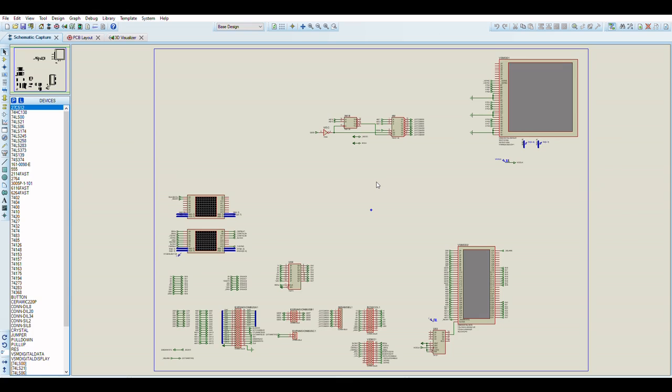So the software I'm going to show you has allowed me to transcribe the original Bomb Jack schematics that I found in a PDF file, and to change the operation of Bomb Jack hardware from ROM-based static graphics to RAM-based graphics, and also adding a whole bunch of extra functionality in terms of rendering larger sprites, but also adding extra functionality in terms of what's called a Mode 7 layer.